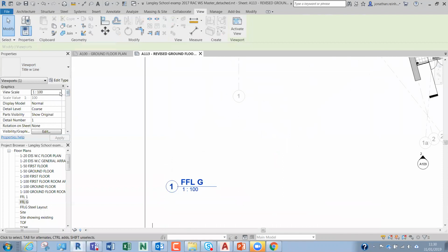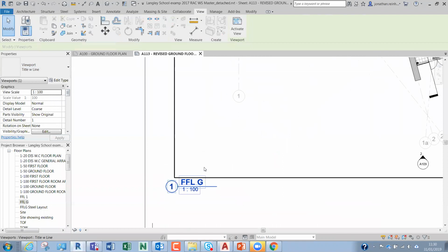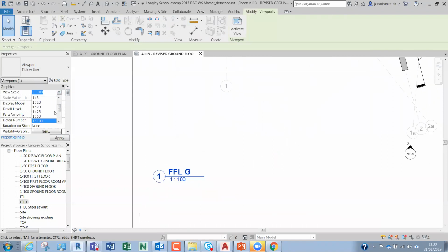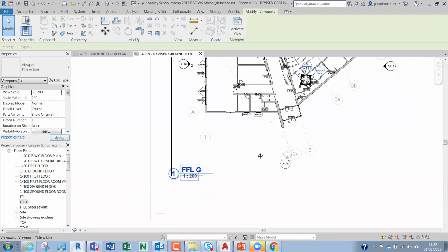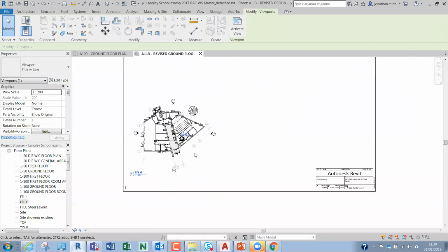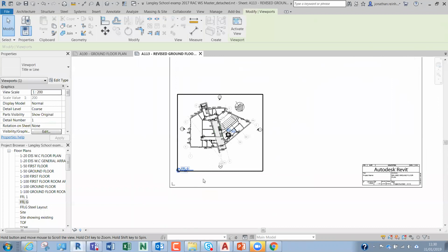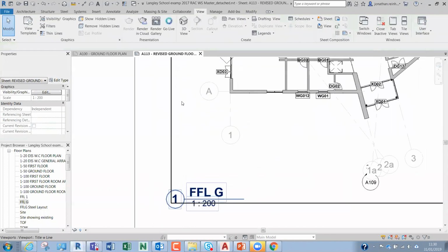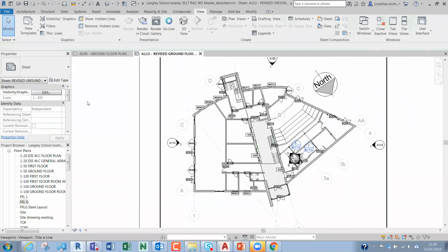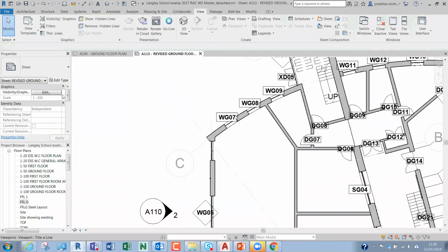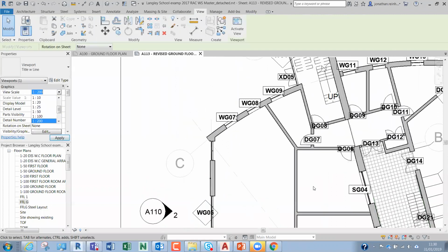This is something I've often seen issues with, especially with planning, where the wrong scale could have been left on the CAD drawing for whatever reason, and there's an issue with the local council as a result, and therefore you might have an issue with your planning application. So you can see how that's updated there. What it also does when you change the scale, it also determines what to show on the drawing and what not. So as you go into less detail, if I was to go down to 1000, it's going to show less information on the drawings as well.